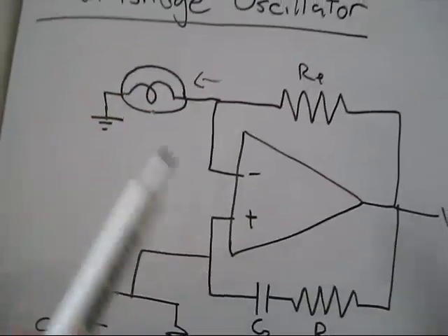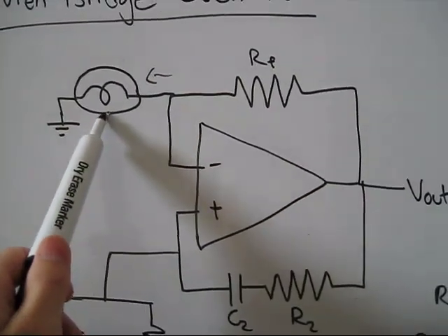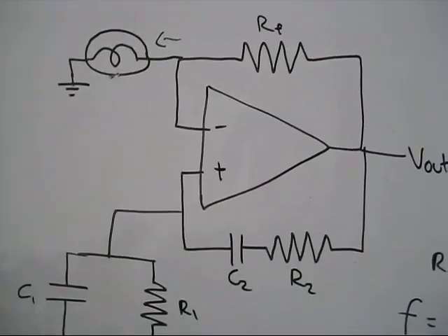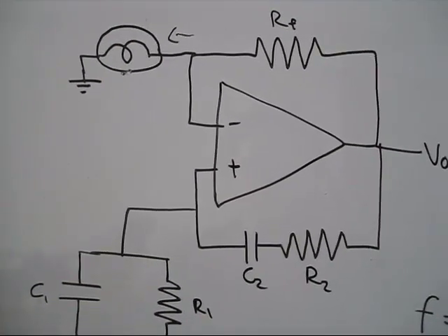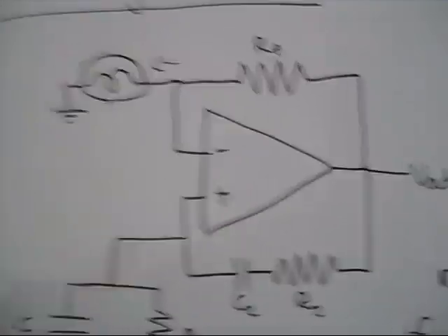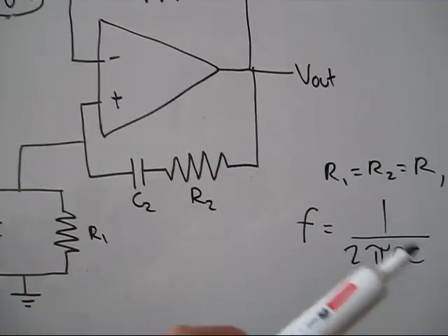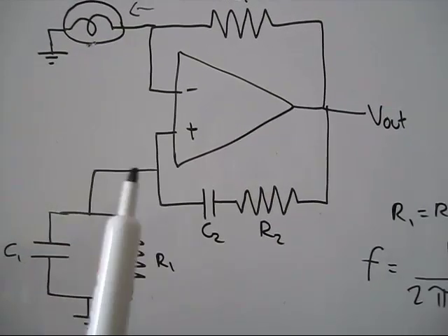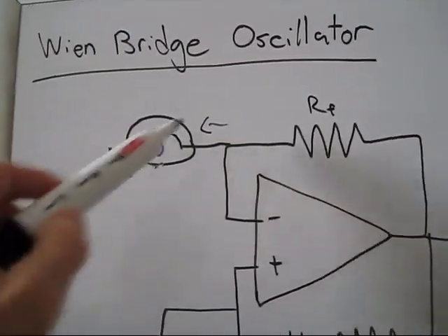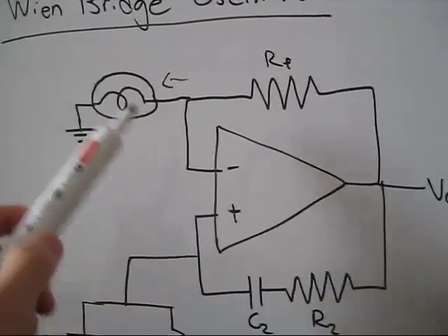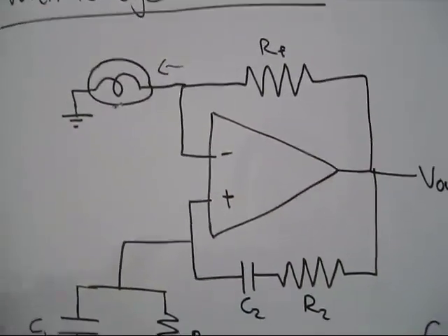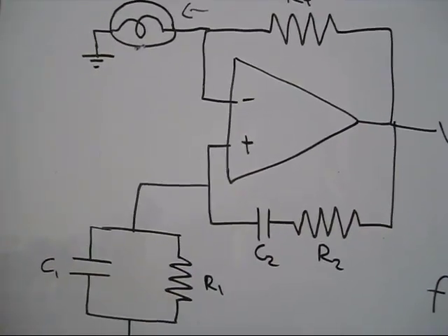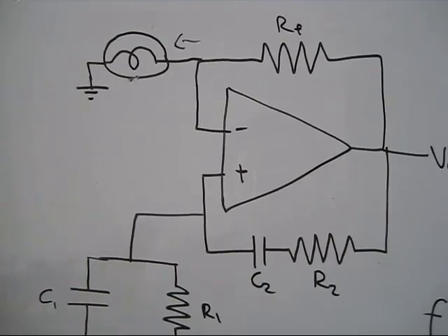Something like that. You can look it up on Wikipedia, but I don't think any of you are actually going to build this oscillator with a lamp in it, especially nowadays with light bulbs being substantially different than they were back then. You can modify this circuit a little bit, right? Let's say you put just a regular resistor there for your gain instead of a lamp. Well, now unfortunately you don't have that amplitude control anymore, so you're not going to get a very nice oscillator.